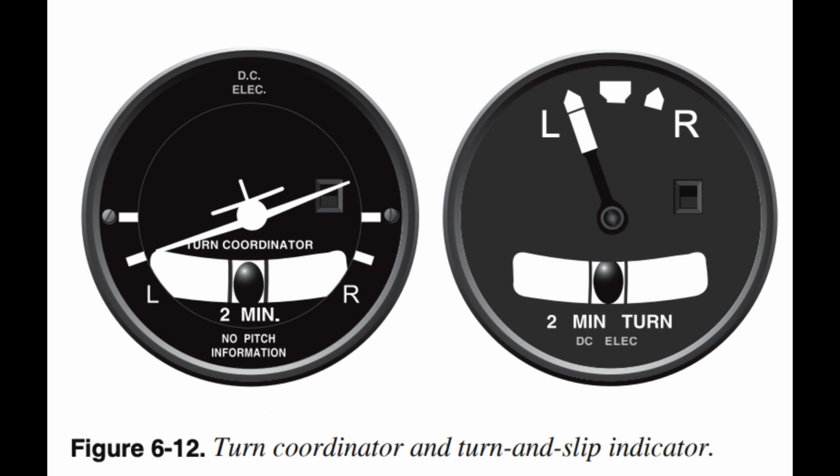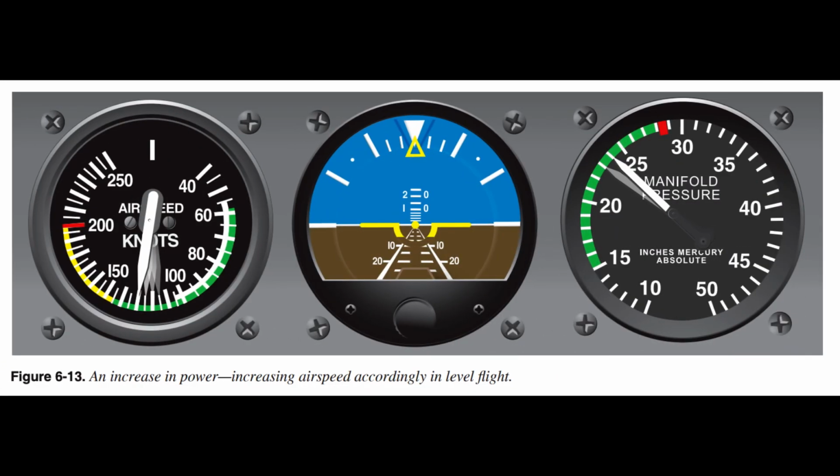Power control. A power change to adjust airspeed may cause movement around some or all of the aircraft axes. The amount and direction of movement depends on how much or how rapidly the power is changed, and whether it is a single-engine or multi-engine airplane or helicopter. The effect on pitch attitude and airspeed caused by power changes during level flight is illustrated in Figures 6.13 and 6.14.